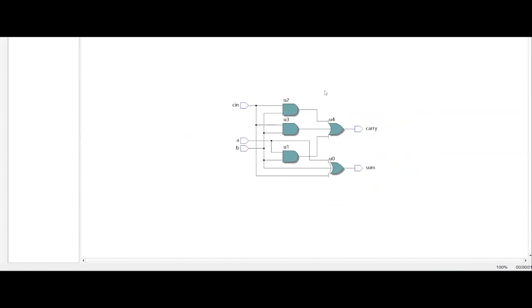We are applying a stimulus to the design inputs and checking the output, that is nothing but simulation. Everyone got that? How are we applying the inputs? Based upon the test bench. We create the test bench, apply the inputs to the design, and verify the output. That is nothing but simulation. Everyone got the difference between synthesis and simulation?